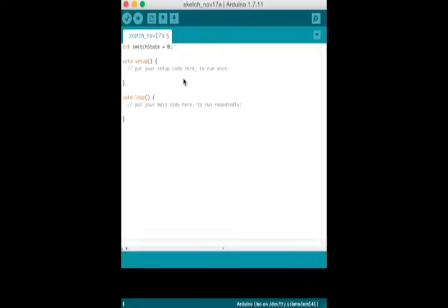And so this is configure pin functionality. The setup runs once when the Arduino is first powered on. This is where you configure the digital pins to be either inputs or outputs using a function named pin mode. The pins connected to LEDs will be outputs and the switch pin will be an input. Okay, so they have written, let's get rid of this, pin mode